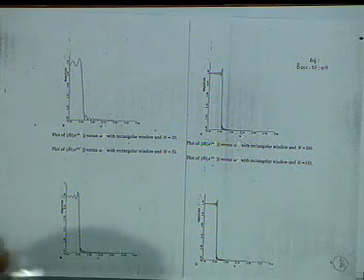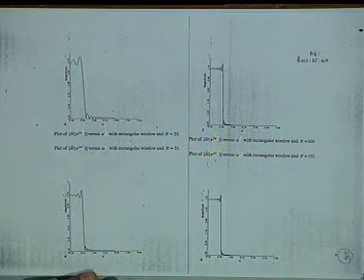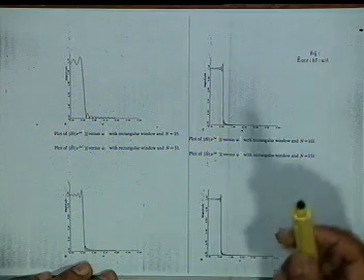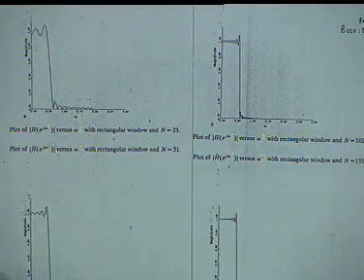To show the Gibbs phenomenon, I shall project a diagram here which shows the Gibbs phenomenon in effect. This is an approximation of a low pass filter, that is, we take e to the minus j omega tau, and this is the picture for capital N equal to 25.